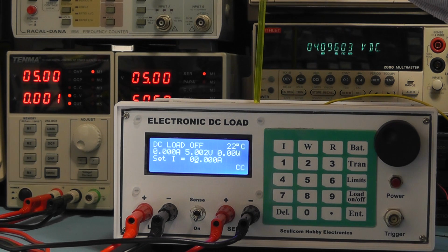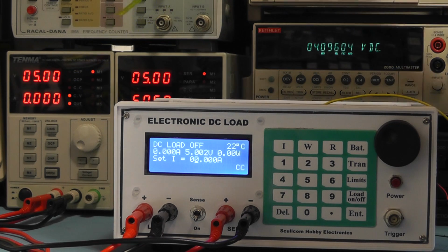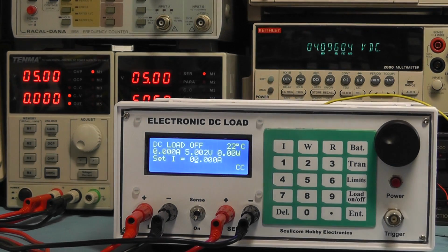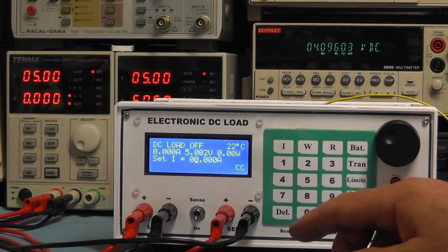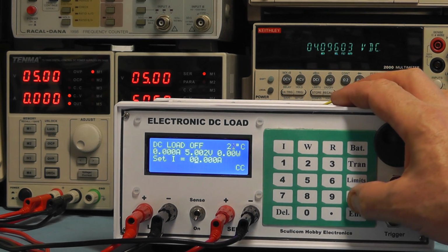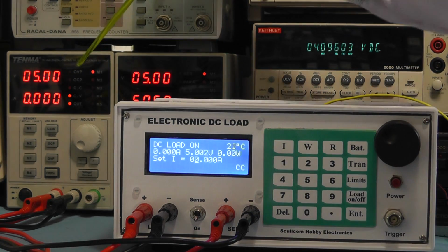So it's just about there now. There we go. And once you get to 0, stop, don't go any further. If you're not sure, just back it off a bit to 1 and then just tweak it slightly. So that's now set to 0, we've got no leakage current. And just to double check, this is with the load off, so let's just switch the load on and make sure that the leakage current is still 0, which it is.